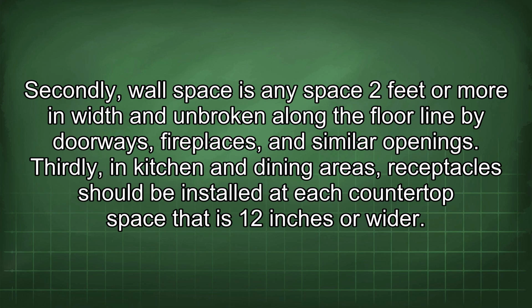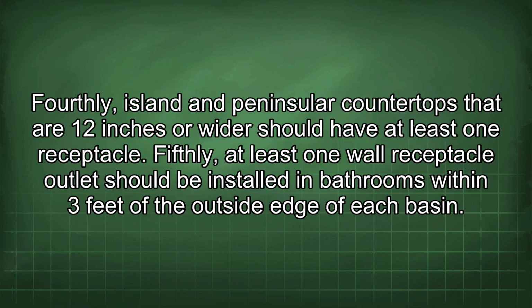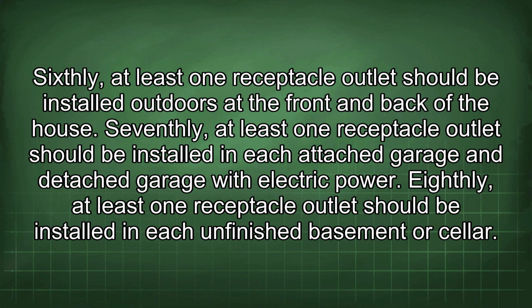fireplaces, and similar openings. Thirdly, in kitchen and dining areas, receptacles should be installed at each countertop space that is 12 inches or wider. Fourthly, island and peninsular countertops that are 12 inches or wider should have at least one receptacle. Fifthly, at least one wall receptacle outlet should be installed in bathrooms within 3 feet of the outside edge of each basin. Sixthly, at least one receptacle outlet should be installed outdoors at the front and back of the house.